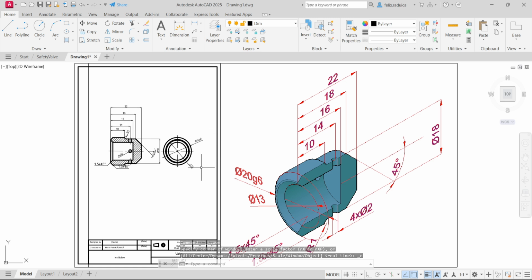now scaled according to the 2:1, so the shape, the dimensions of the shape of the drawing. This is at 2:1, so it's enlarged, but the dimensions themselves, the measurements here, the values placed on the dimension lines, are the ones corresponding to the real part. So this is how you use the scale and how you think about enlarged scales.